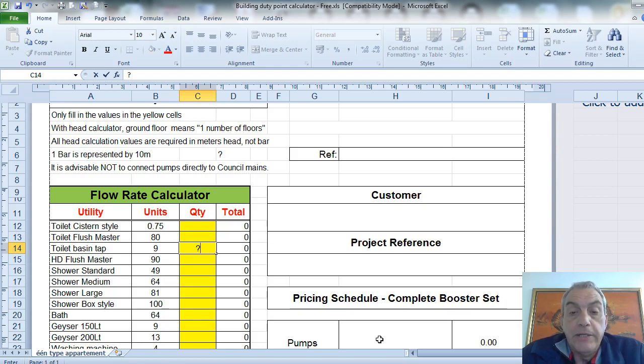When I say multiple outlets, for argument's sake, an office complex where you would have 3 or 4 ablution blocks in the whole premises, a couple of garden taps, maybe a canteen on the premises, or an apartment block where you might have 20 or 30 apartments in a block, and you'll obviously have a variation in flow rate and a variation in your pressure on the system, and you need to actually do a duty point calculation to be able to do a selection on a pump.